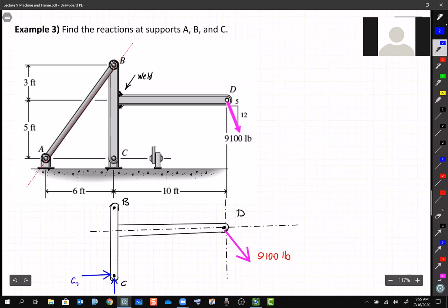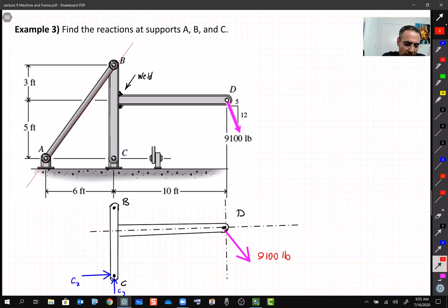And then the two, the AB link. Okay, what is about it? So we'll draw a two force member. Exactly. So it's a two force member. If it's a two force member, always apply load in the line of action between A and B.